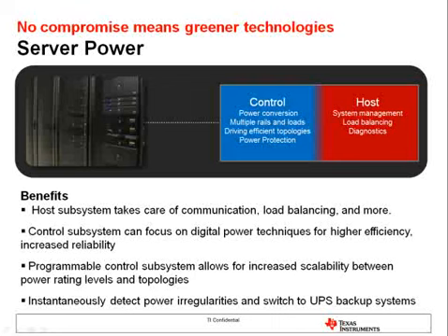This is where the C28X really shines. The math capabilities and precision peripherals lend themselves perfectly to these requirements. By being able to drive multiple rails independently, the C28X side of Concerto will be able to handle different loads on each of these rails and dynamically adjust each profile to maximize efficiency. However, that's only half of the story.